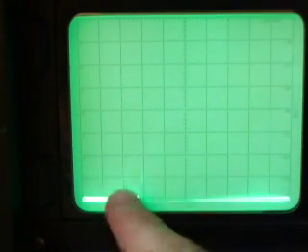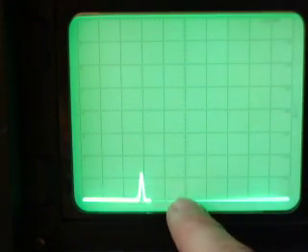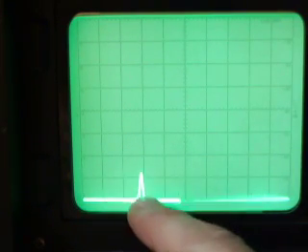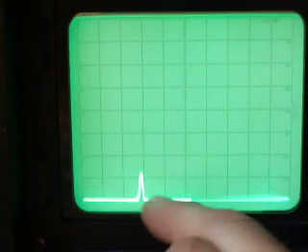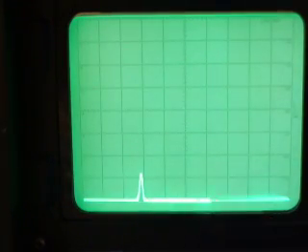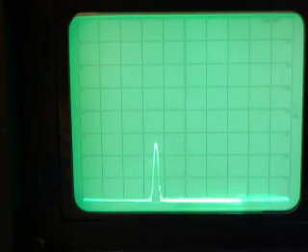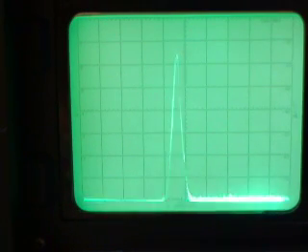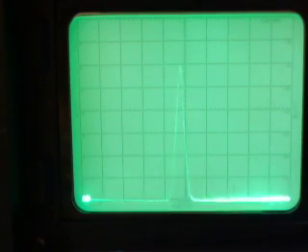Now this spectrum analyzer is currently set at 1 kilohertz per division, so I'm only 2 kilohertz lower, maybe a little bit more, but 2 kilohertz lower from where I was at my peak. So what I'm going to do now is wind it right the way through again, and we can see that it rises and rises until we get, there's a bit of a dip there, and then it seems to rise again till we get to what's around the center frequency, which seems to be around there-ish, which again is 9.9976 megahertz.